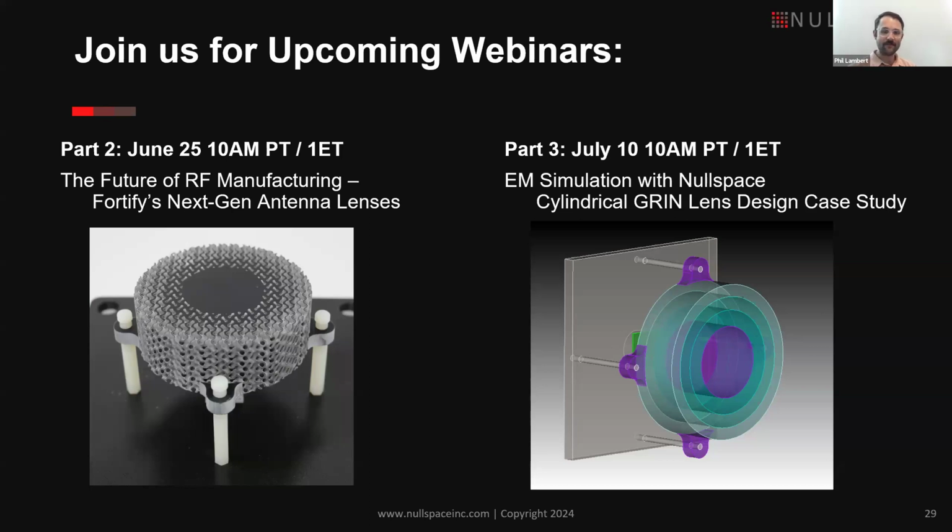And that means that based on the volume fraction of air to dielectric within a region, if you were to measure that, that would be the effective dielectric constant of that small region. We've done a bunch of characterization of this through waveguide, through free space test methods, and in physical part measurement to validate our approaches. But effectively, what we mean when we say effective dielectric constant, or effective DK, refers to the ability to tune the dielectric constant of a specific region by using that latticing approach.